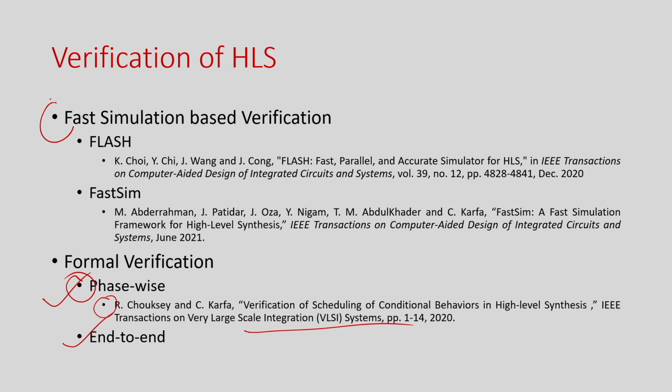In the context of simulation based verification, we have to simulate the generated RTL with some input. I have to simulate the C code with the same input, and I just compare whether they give the same output or not, right. That is simulation based verification, and I have already explained in this course that simulating RTL is much slower than simulating a C code, because the RTL simulator is cycle accurate, with a lot of detailed information of the data path and controller, so it has to go through all these things.